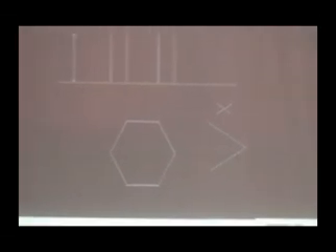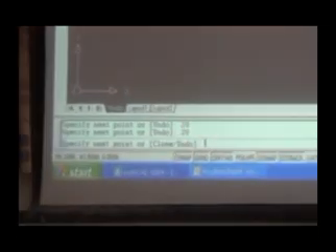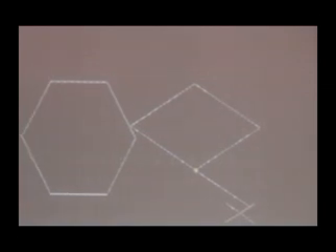X, Y, Z axes, parallel to that. Suppose I draw a line of 20 mm along the x-axis. Then along the y-axis I want to draw 20. I am keying in the distance in the command prompt: 20 in the y direction. Again along the x direction, 20 I am giving. Again here I can end it. So this is a square plane I have drawn.